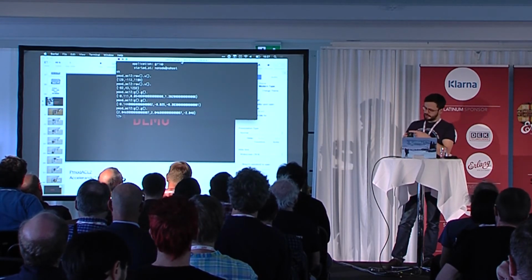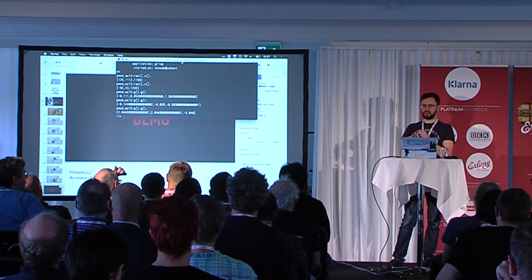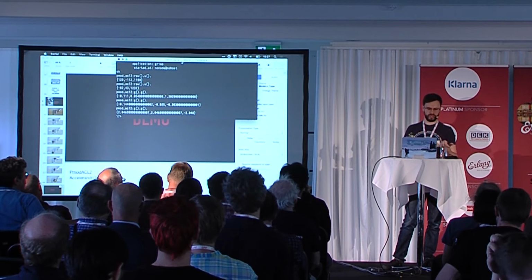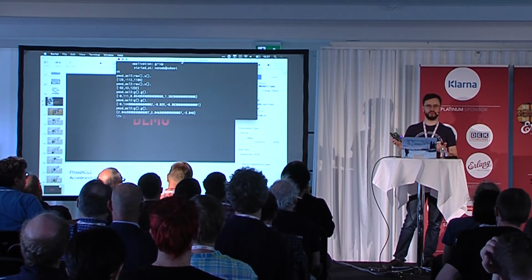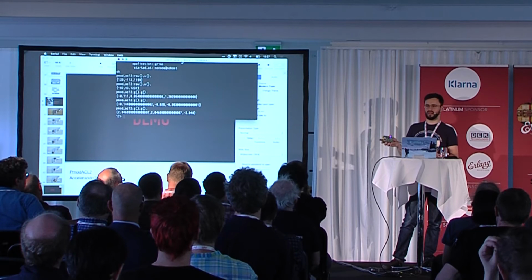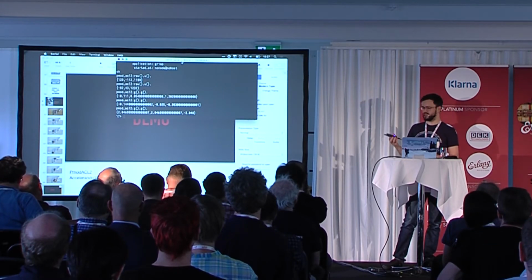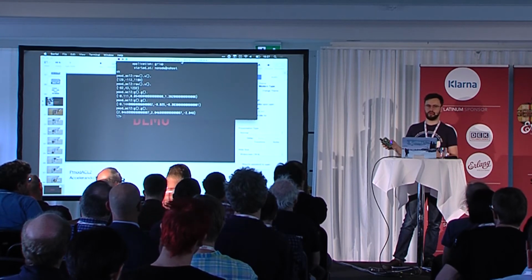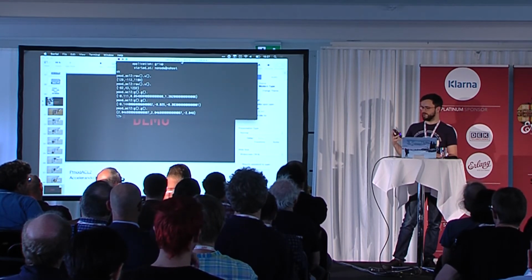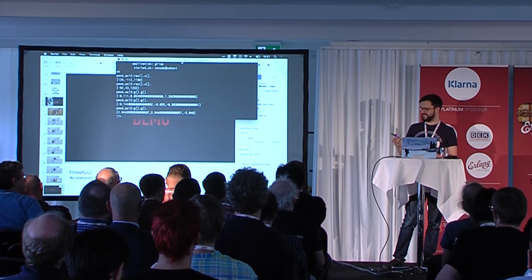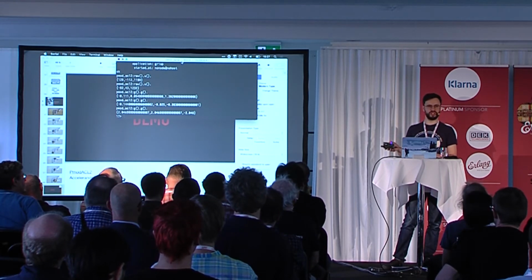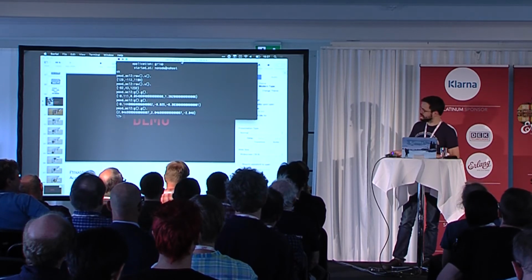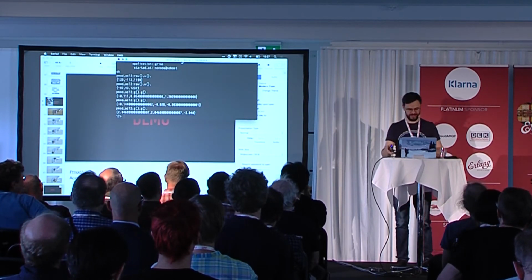By default, it's in a 2G mode. This one has up to, I think, 8 Gs, and the Pmod NAV, the cool one, has up to 16 Gs force detection. But the accelerometers themselves actually handle much more, because it's an electromechanical sensor. I think the specification says it can handle up to 5000 G without breaking. I'm not sure I'm strong enough to test that, but I'm at least strong enough to produce 2G, which is nice.